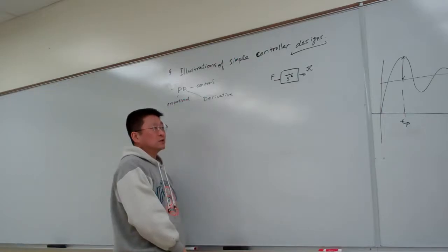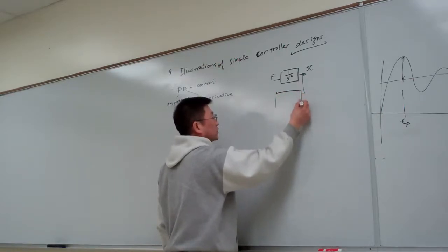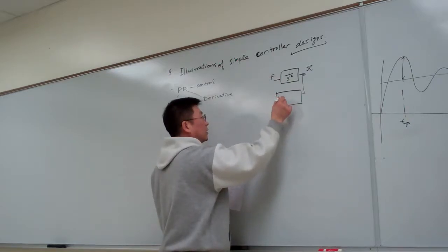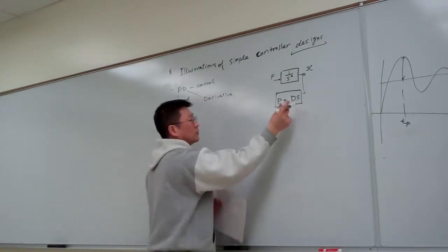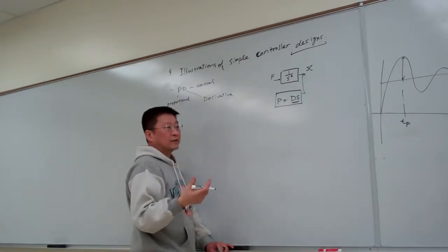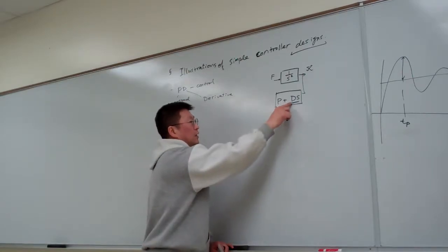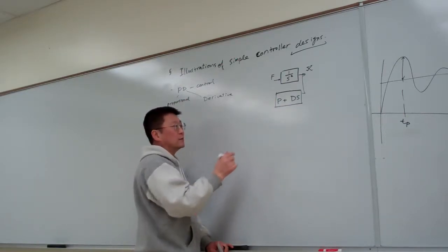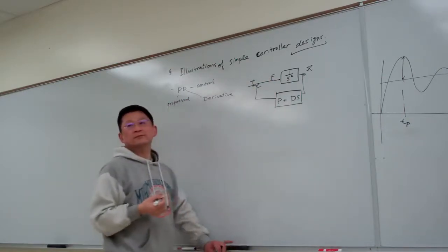If we want to change the dynamics, basically we can add feedback. We simply add a proportional control, which we call P, and also a derivative control, or speed control. This is equivalent to adding damping, viscous damping. And the proportional term simply adds a certain negative spring feedback. So we put into the feedback something like this.